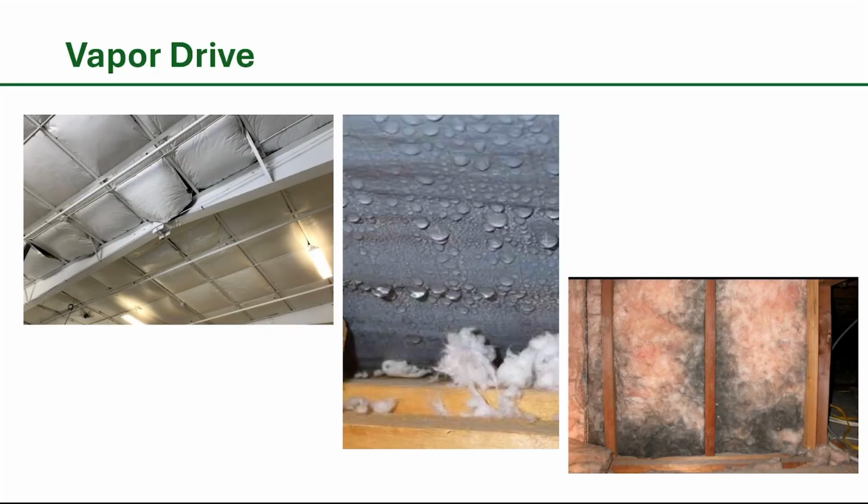The way we solved that one was we added continuous insulation over top of the roof deck and single ply membrane on top of that to keep that steel warm. No more condensation, no more leakage. If you ever pull a wall apart, you see fibrous insulation.